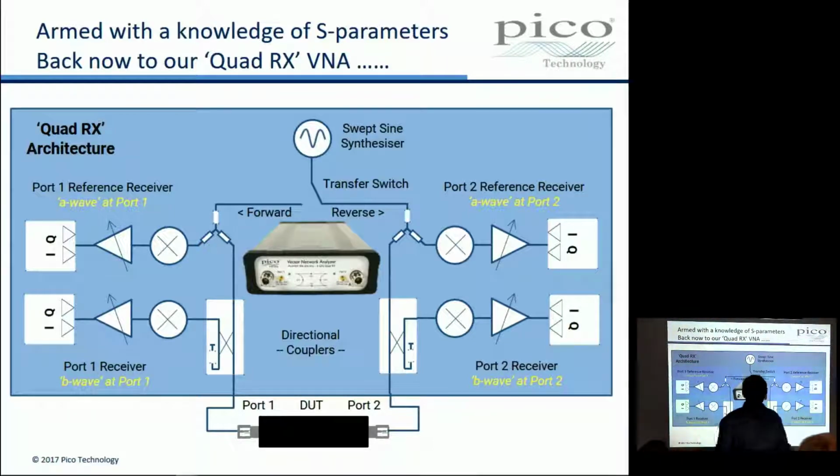Armed with the knowledge of S parameters, does that arm you with the knowledge of S parameters? Yeah. Got it? And when the VNA 106 saves an S parameter file, or Touchstone file rather, can you choose whether it's magnitude or is that fixed? It's real and imaginary at this point. One of our software enhancement requests is that you can change it. But when it saves and when you load, it's real and imaginary. Right, and there are utilities around to read and convert and all that, yeah.